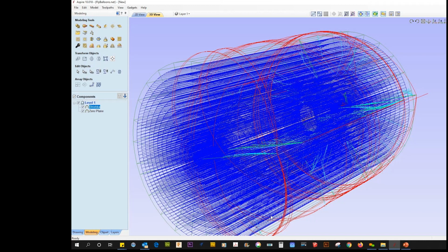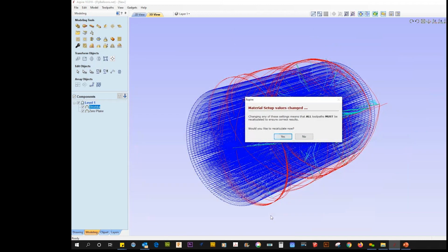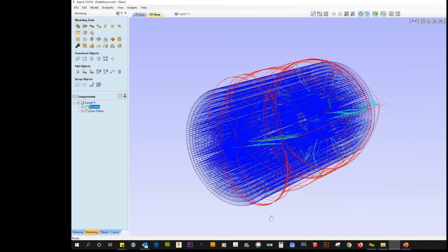Doing it this way is the shortcut. If you put the diameter size in there from corner to corner, then these values here will compensate to here, so that means you still will have your clearance. So that's something to keep in mind. And then we're going to do a finishing path.